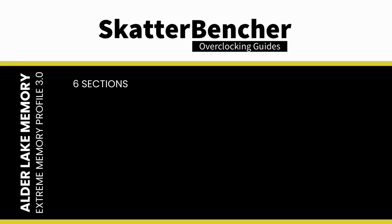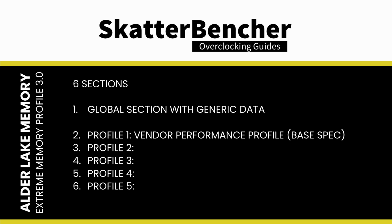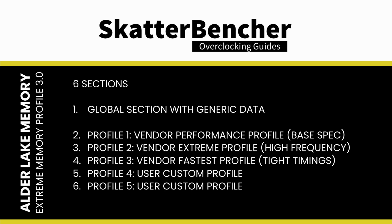The XMP 3.0 standard is designed with 6 sections. One global section describes the generic data which is used across the profiles. The 5 other sections are designed for 5 profiles respectively. Profile 1 is meant for the performance profile. This is the standard XMP as we know it. Profile 2 is designed for the extreme settings. This could be a higher frequency at a higher voltage. Profile 3 is designed for the fastest settings. This could be tighter timings at higher voltage. Profiles 4 and 5 are rewritable and meant for user custom settings.